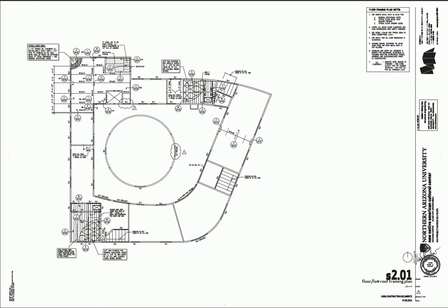I'm going to go to the next page here. You can see this says framing plan. So framing indicates that it's structural. So I might concentrate a lot down here on the titles of the pages. You can see right below here that these were issued for 100% construction documents, so I expect them to be complete. This has floor and low roof, so I'm looking at this saying, okay, some of these spaces here look like they're open, and some of them look like they might be floors, and some might be roofs. So I'm not quite sure what's going on.